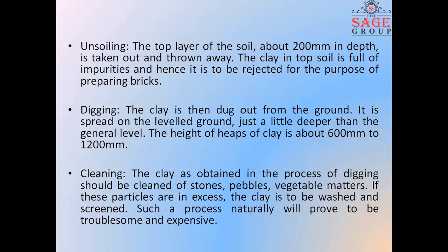Then after the digging process, the cleaning process occurs, in which it should be cleaned from the stones, the pebbles, the vegetable matters. If some organic matters occurs, plastic, all the materials should be separated out. If these particles are in excess, then the clay is to be washed and then screened. Such a process naturally will prove to be troublesome and expensive. That means if the soil contains most of the impurities, then the suggestion is that new sites should be selected for the digging process.